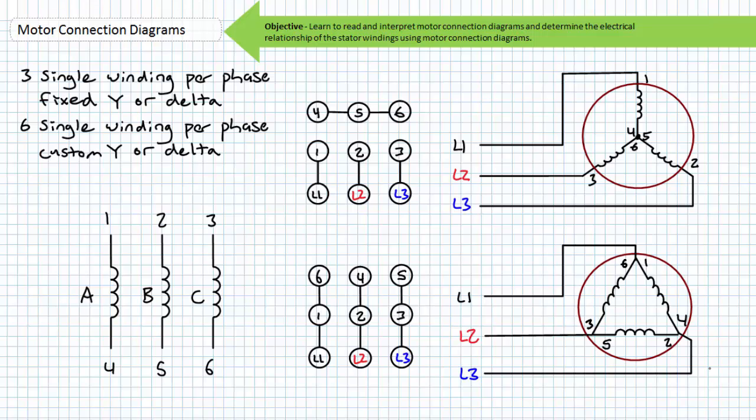However, as a brief overview, consider a motor starter that starts a motor in the Y configuration and then transitions to the delta configuration after a predetermined length of time or after the motor has come up to a predetermined speed. When started in the Y configuration, each winding receives the smaller line-to-neutral voltage, and voltage, being the cause of current, inrush current will be less.